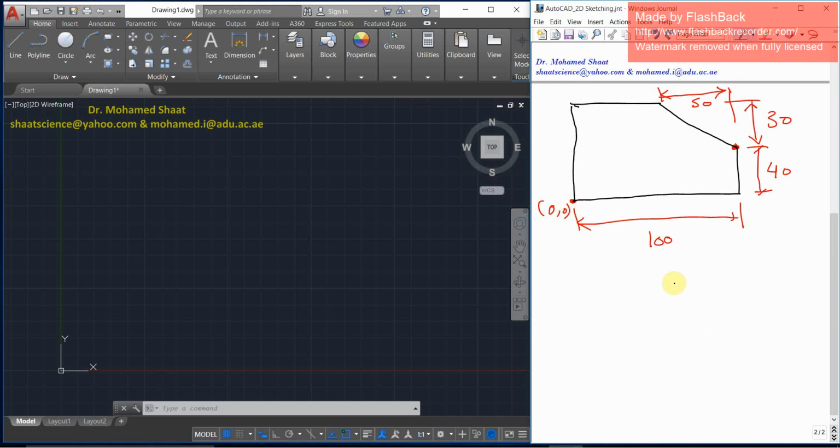In AutoCAD you aren't going to find a complete circle, but instead the circle is broken down into very small segments. There is one segment, then another segment. All of these segments, we calculate and arrange them together, so that when you see them, you see a virtual circle tangent to all of these segments together, forming a circular path, but it is not 100% a circular path.